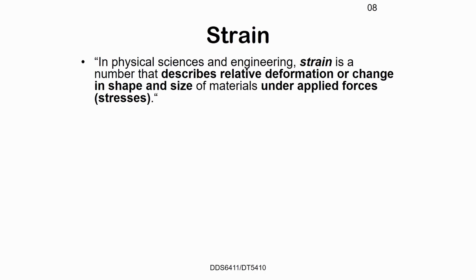We've just talked about stresses. What about strain? So this is like average deformation. When you pull on something, it's going to get longer, right? But for ease of comparison, if you pull on a long rod compared to a short one with the same force, you're going to get different elongation. You're going to get more deformation when you pull on a long rod. Smaller deformation from a shorter rod with the same force.